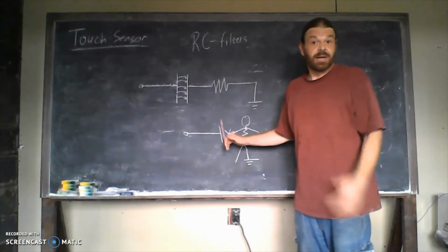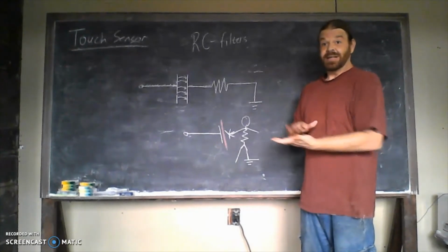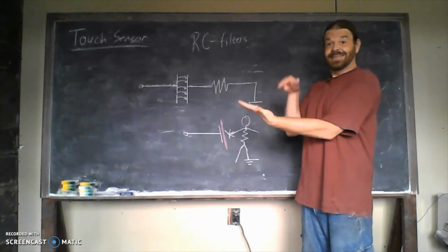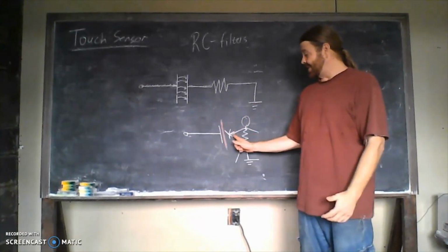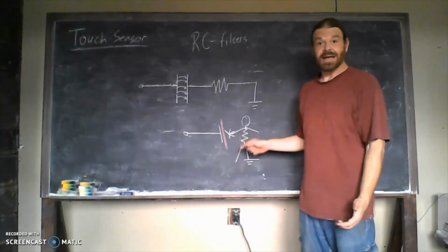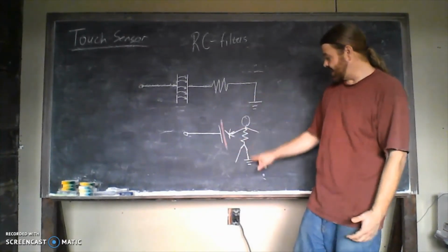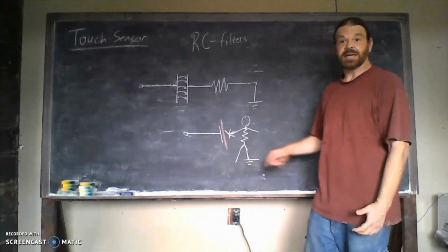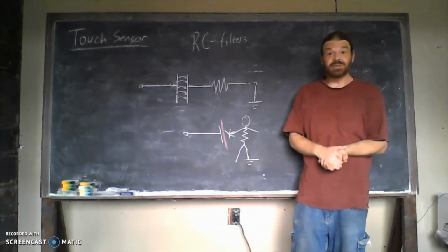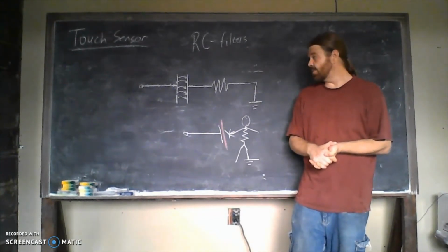And for what this is leading up to, one good dielectric material would be a thin matrix of LEDs to produce a screen. Then it separates our hand from the other side of the capacitor, so we get the capacitance. And there's a gap there, so we get capacitance, and then the human body serves as resistance back to ground to finish out an RC filter. And that's all there is to these sensors. So let's go plug up a circuit and see how it works, and hopefully it'll make a little more sense.